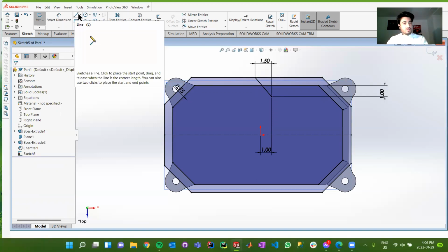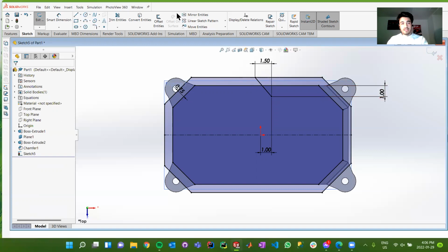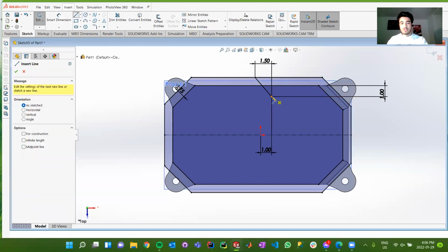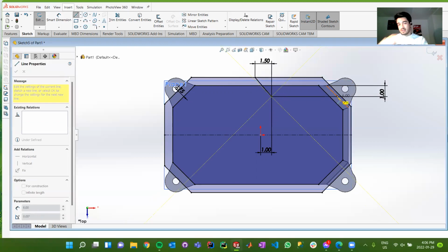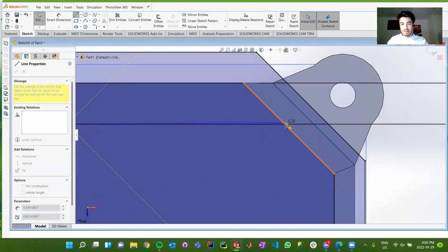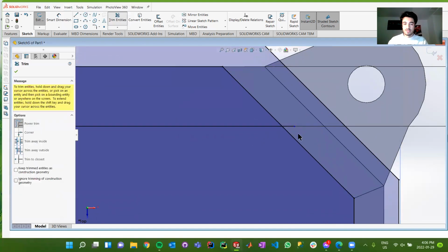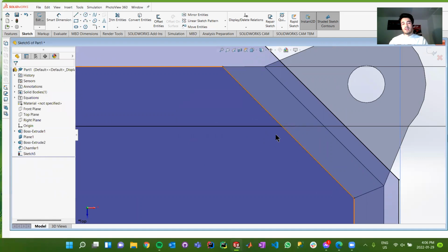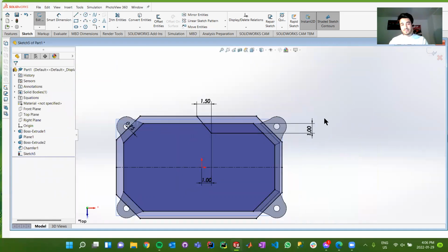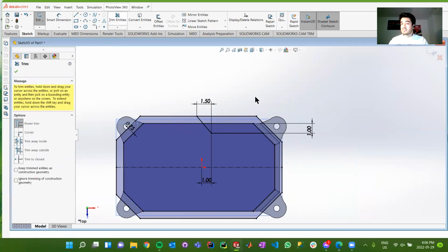And then from there, we can just essentially extend this line as such. I'm not going to use the extend tool because it'll just extend it diagonally. I want to extend straight, essentially. So we can either use the trim tool or just forget about it. I'm just going to forget about it and make this as horizontal as possible. And press OK there. And now this is looking a little bit more fancy, a little bit more palatable, if you so wish to call it.